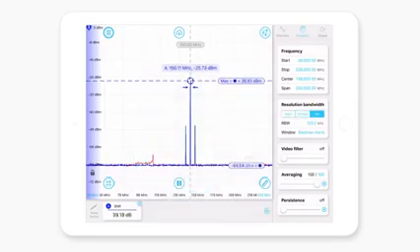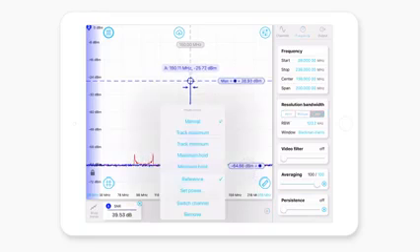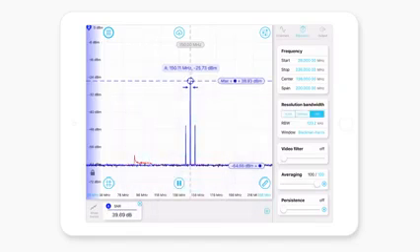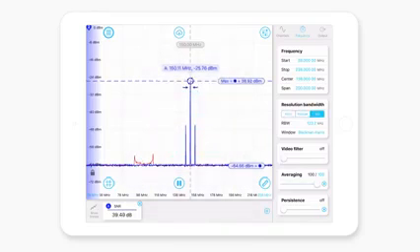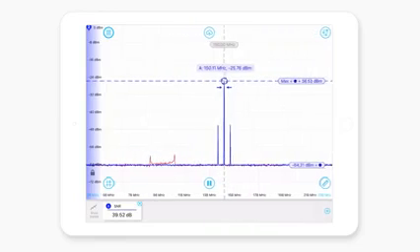So if I did it with cursors, what I've done here is actually set this bottom one as a reference. And then this one at the top is tracking the maximum. And so the measured SNR here, based on that reference, is 38.85, but the actual cursor measurement here is about 39.5, and it's doing a calculation of the actual noise in this span here. So that's pretty clever. Also a very handy tool to have. Cool. So I think that's about it.